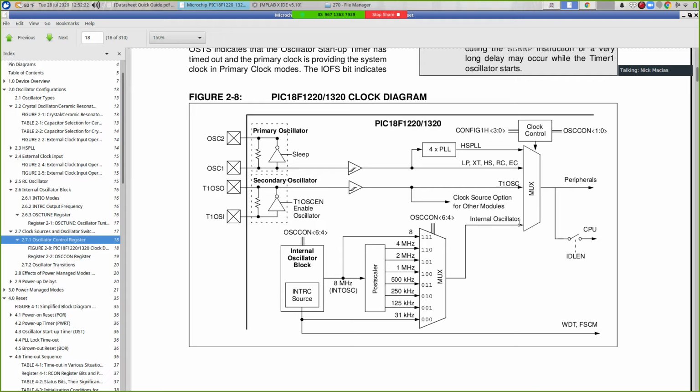No, the 555 does not have a crystal. It's what we call an RC circuit. So if you take a resistor and a capacitor and you hook them up in a pretty simple configuration and you analyze them, you start finding trigonometric terms in the solution of the voltage equations. And so they're oscillating.